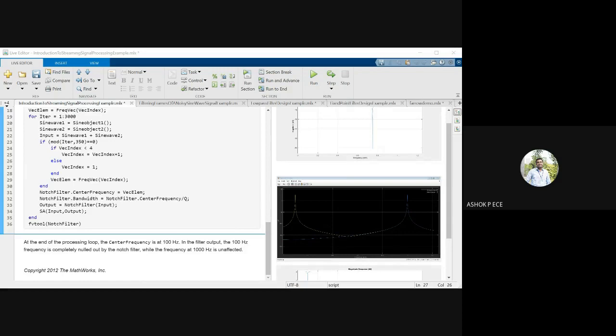So what we have used here is the component called a spectrum analyzer. In the spectrum analyzer, you can have a lot of functions. See here, you can do anything in the spectrum analyzer. You can use the peak finder to find the peak. When you keep the diagram here, it will show the peak. The peak value happens at